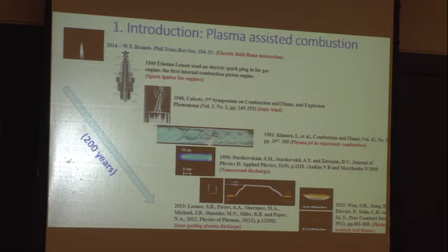If you calculate at, let's say, 600 Kelvin and 1 atmosphere pressure, it probably takes about a second for auto ignition of a cool flame, low temperature ignition. But with a plasma, you can accelerate the ignition process by 2 or 3 orders of magnitude, allowing you to observe the cool flame, as you can see here. So this gives you a highlight that in the 2000s something is changing.